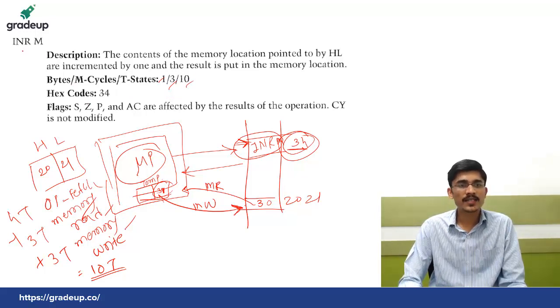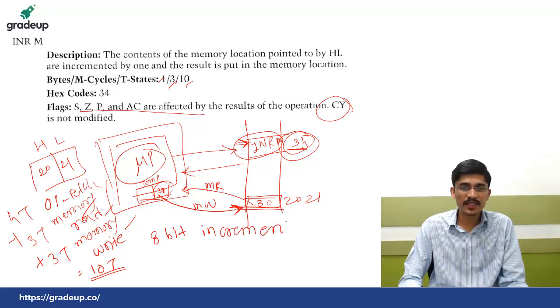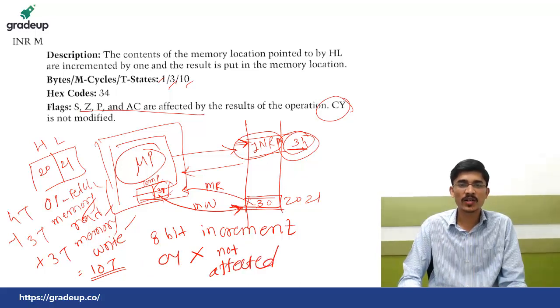All the flags are affected except the carry flag, because it is an 8-bit increment. Whenever there is an 8-bit increment, the carry flag is not affected.